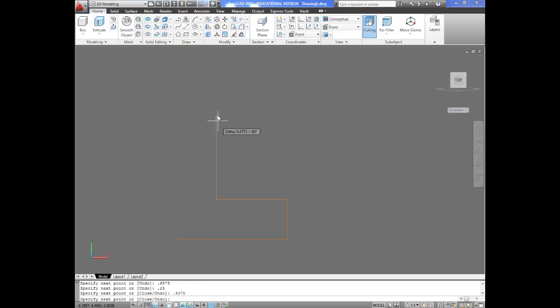I could keep going, but I'm going to terminate the command and then call it back, and I'm going to draw the line back here. Our mirror line will be this one, which will be 1.5, and then I'm going to go horizontal half of the total distance. The total distance of the wheel will be 1.5, so this will be 0.75. I'm going to go down 0.125. I'm going to go back to the point where we ended up, right here. I'm going to go vertically at a distance of 1 inch.